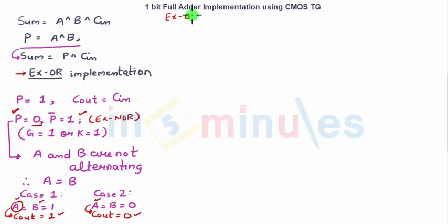So this is XOR with inputs A, B and output Y: 0, 0; 0, 1; 1, 0; and 1, 1. Output is going to be 0 here, 0 here, and 1 in the other two cases. So this is my XOR. We have already done this. If we make B our select line, it says that if B is 0, 0 for a PMOS, then my output is equal to A. Because we are using a transmission gate, I'm going to connect an NMOS in parallel.